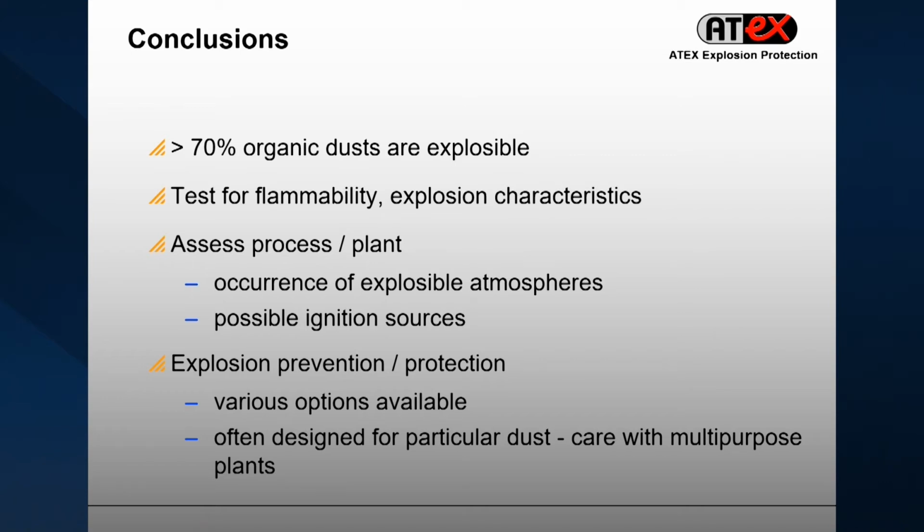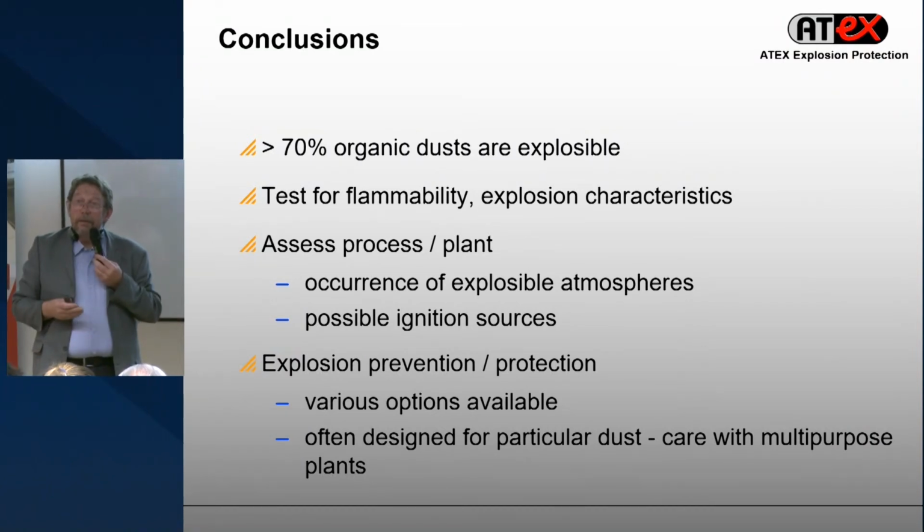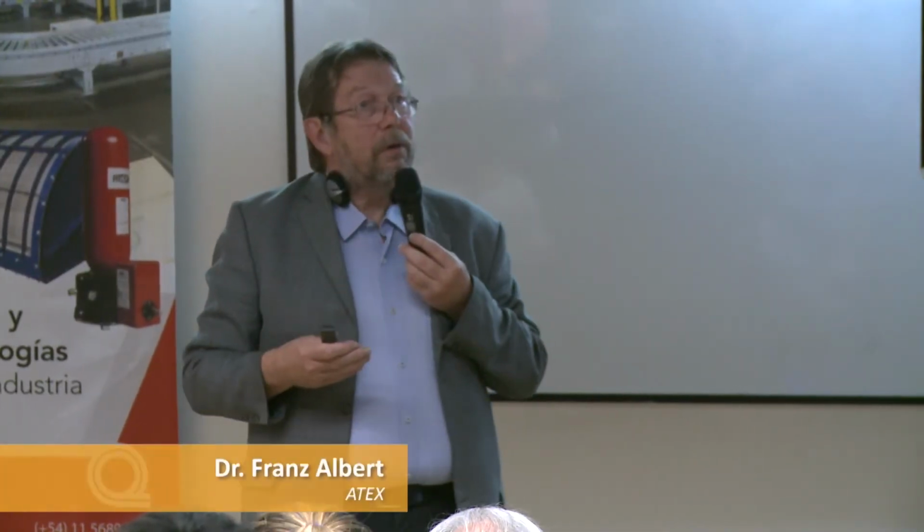In Europe, when we got the law that one had to make a zone classification, many companies decided, okay, all this we make zone 20 and all this is zone 21, without going into detail. But it then took a lot of time to go back on that again, because zone 20 requires a certain type of electrical classified equipment, and that can be very, very costly.